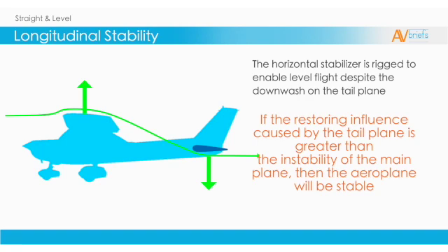This is because, if the airplane pitches up, it produces more lift. That will cause the downwash to have a lower angle of attack on the tailplane. The lower angle of attack will cause the tailplane to fly up, canceling out the mainplane's pitch up.